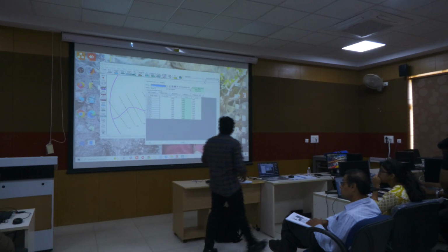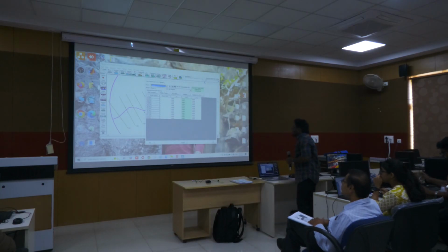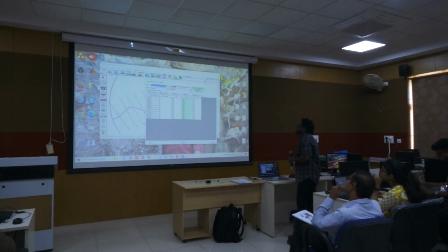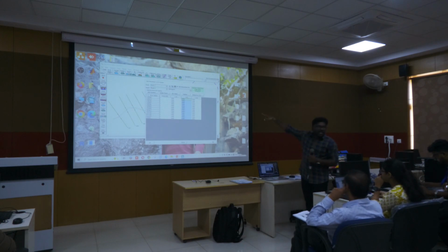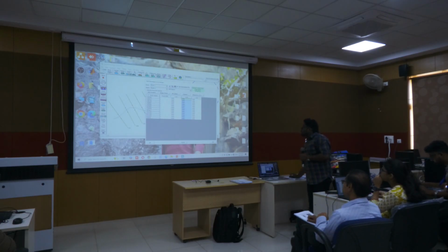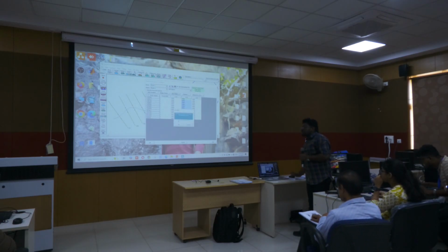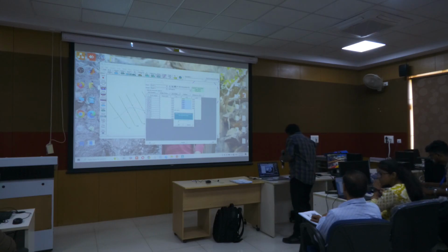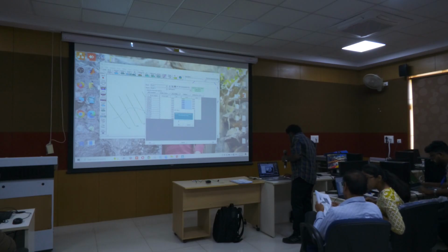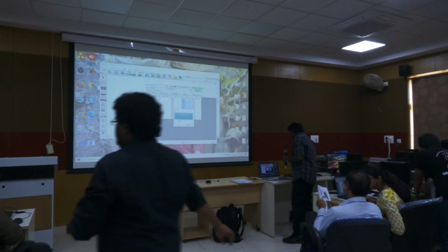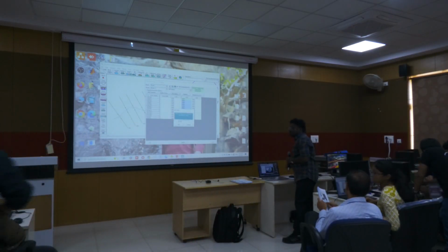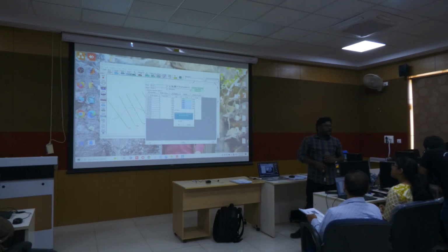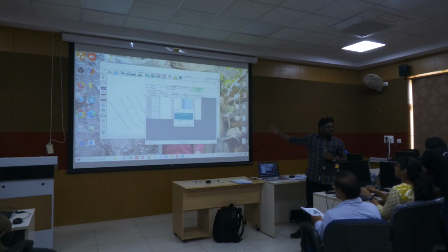So to give the roughness value in the main channel, here just select that row N2, n equal to 2, select here and then click on set values. I am assigning one value, 0.035.